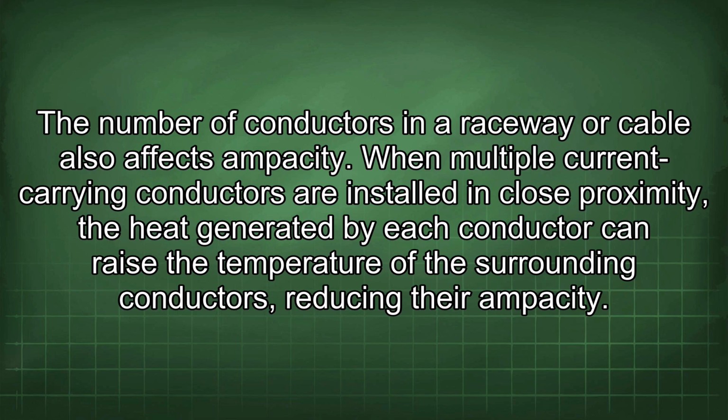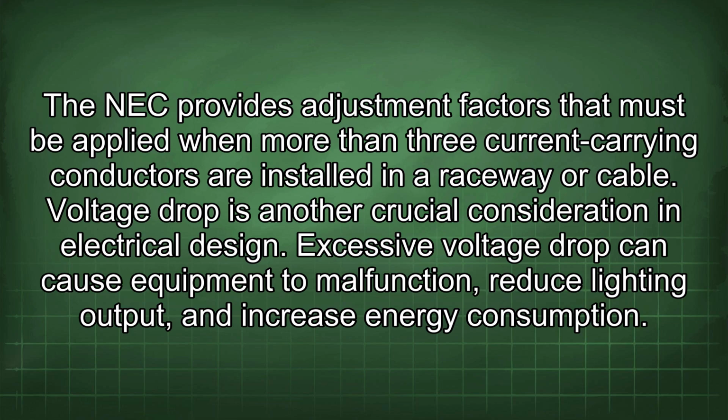The number of conductors in a raceway or cable also affects ampacity. When multiple current-carrying conductors are installed in close proximity, the heat generated by each conductor can raise the temperature of the surrounding conductors, reducing their ampacity. The NEC provides adjustment factors that must be applied when more than 3 current-carrying conductors are installed in a raceway or cable.